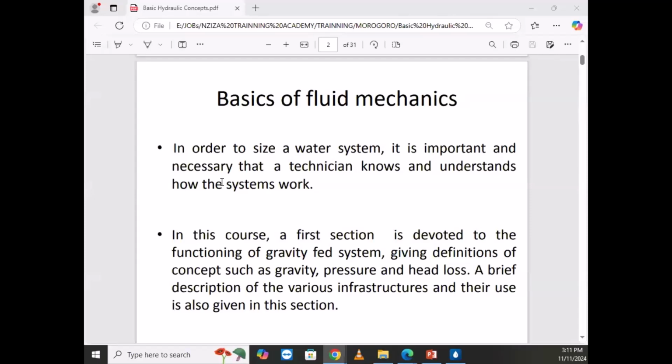In the model, the only infrastructures that matter are the ones that work with pressures, that can cause pressures to change. And here when I say pressures, understand major pressures, not minor pressures, those caused by a valve closing or by reducing a pipe. That doesn't work in WaterCAD, unless you want to go further.